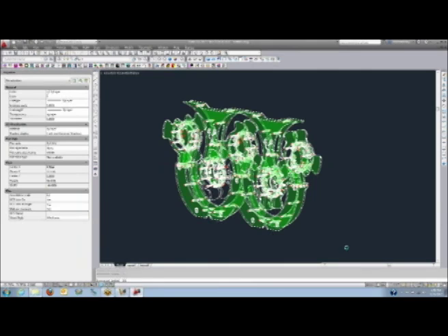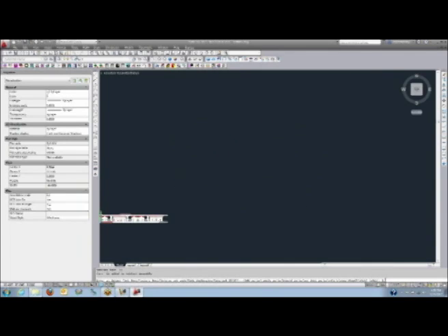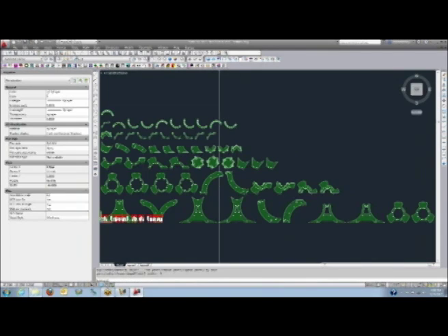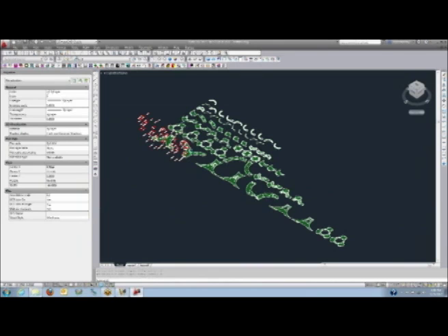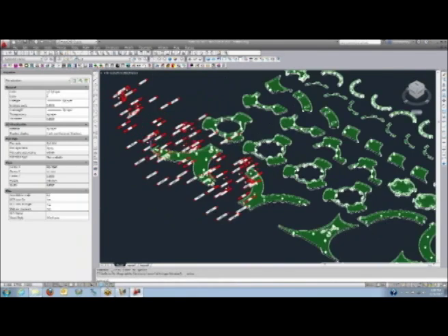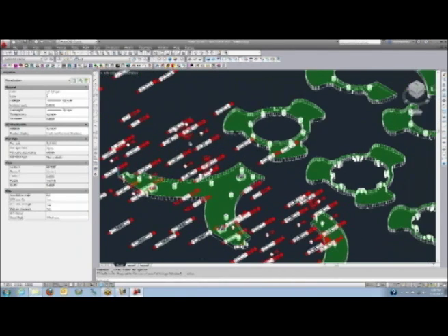Now this assembly has some pins and some other geometry that's outside the scope of routing. My settings will automatically remove those from the list. So one of the nice features here, the parts are recognized with just one click, L for layout. It instantly lays all the parts out flat. So that is the power of the program right there. You can see the pins and the extra geometry that is ignored.